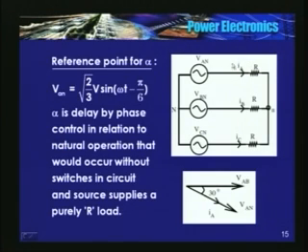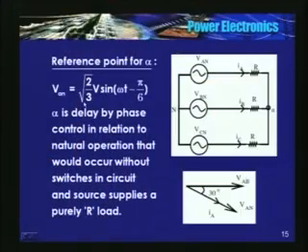So when does this occur? I have defined VAB, the line to line voltage, as root 2 V sin omega t. We know that the phase voltage lags the line voltage by 30 degrees, so VAN is given by this equation, with minus pi by 6. In the vector diagram, VAB is here, VAN lags by 30 degrees, and this current IA is in phase with the phase voltage.